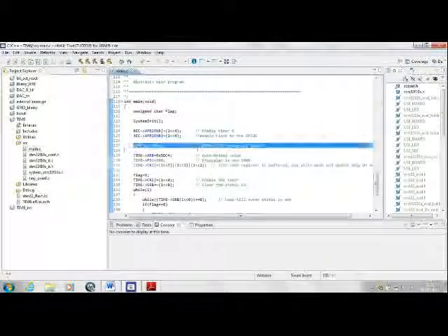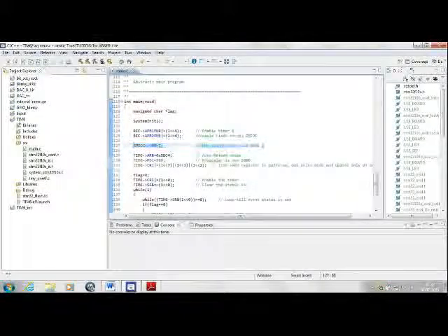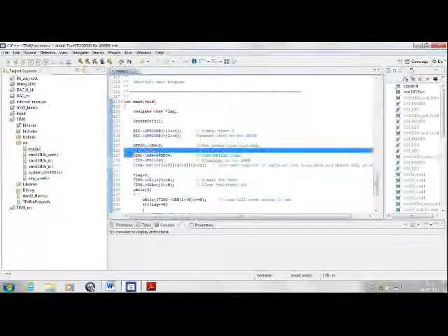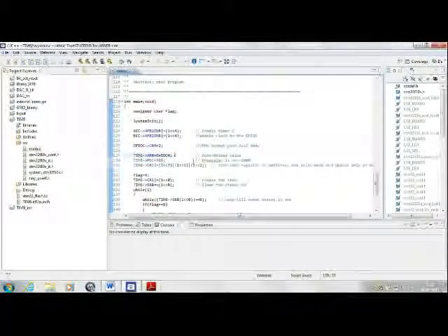Next, this is a very common line by now. We are making sure that the GPIO pin, GPIO C, and that too pin number 8 on this GPIO is configured as an output push-pull mode for a 2 MHz operation. Now, the next line loads a register called the auto reload register with some hexadecimal value.